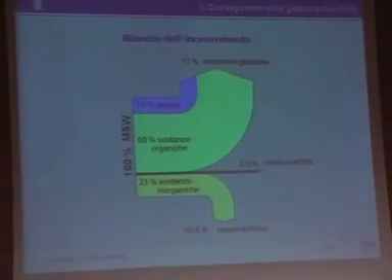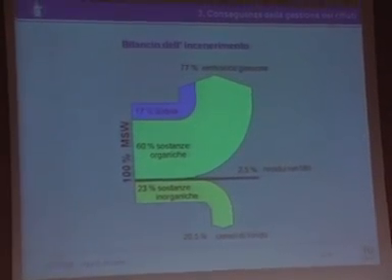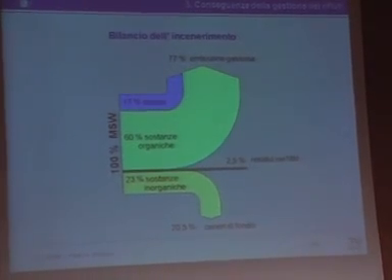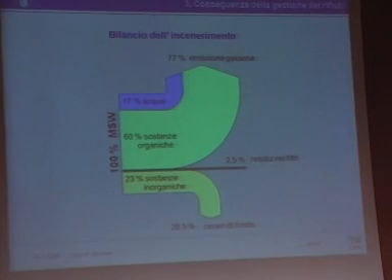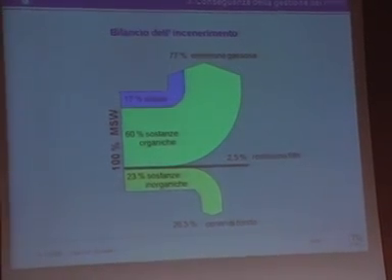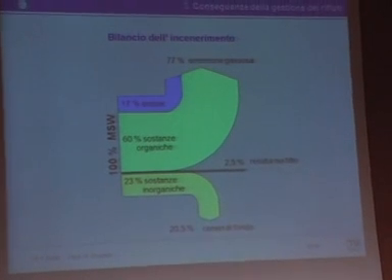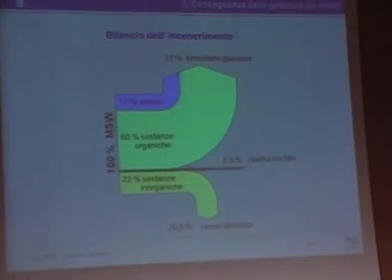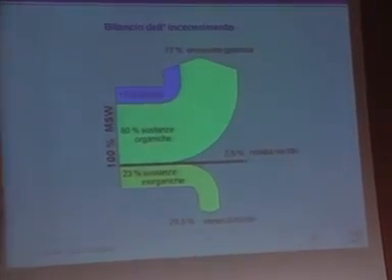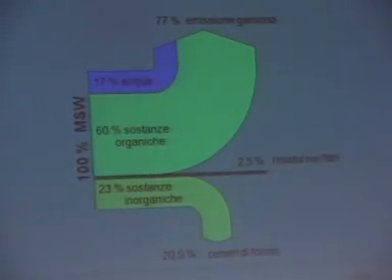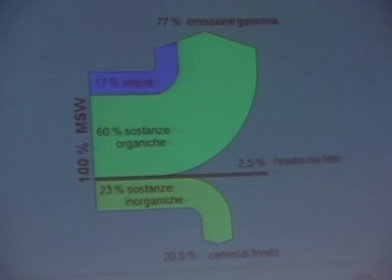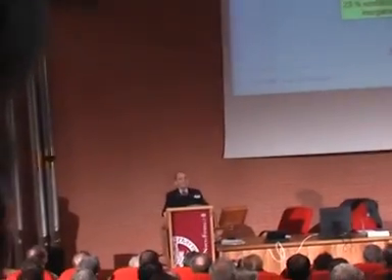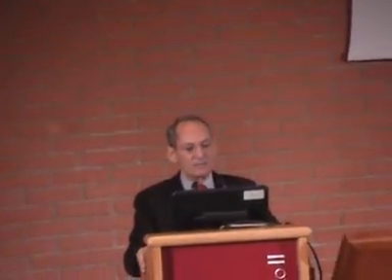The material balance of a modern incinerator shows you that waste is mainly transformed into off-gas. And of course, this off-gas contains a lot of noxious and hazardous substances. Therefore, filter systems, and not just one system, several filter systems are mandatory, and therefore a filter residue will result. The filter residue compared to the input into the plant will be about 2 to 3% according to the filter system and the furnace system.